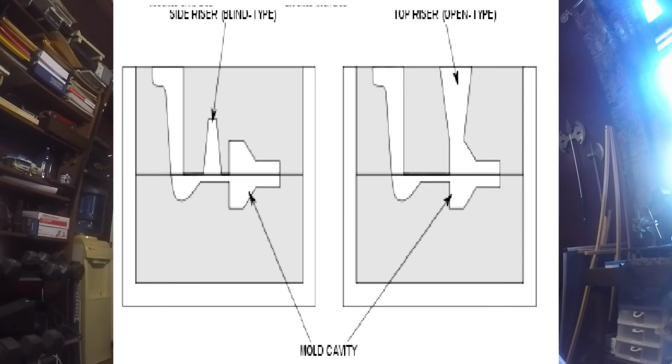The right hand side mold cavity is going to be fed by an open riser. It's open to the atmosphere, and the draft, or the angles shown on that riser, is a good idea, because when you have part of your riser exposed to the atmosphere, that heat is just running away, and so that will start to solidify quickly.